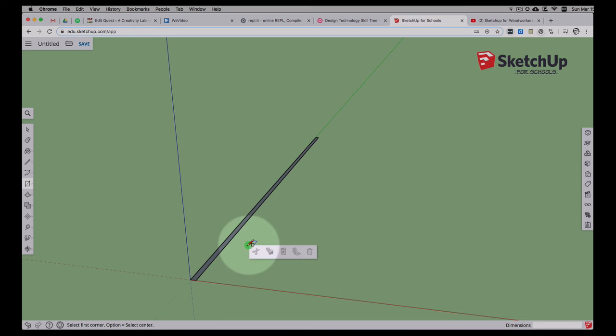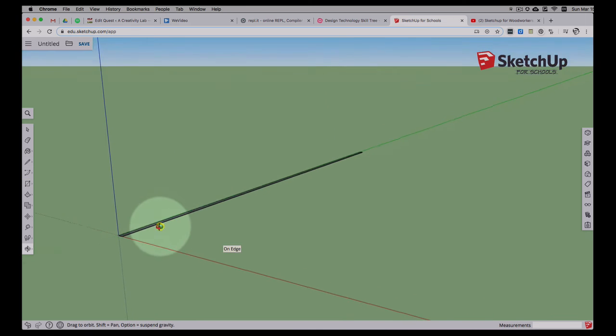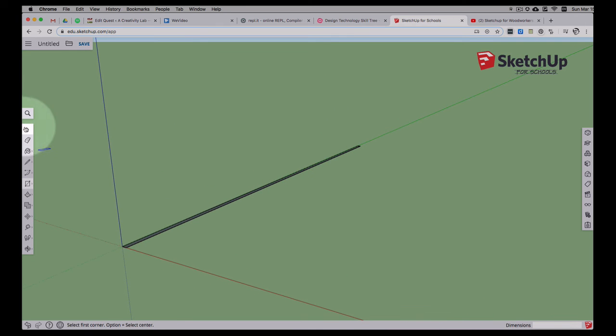Actually, that's probably not going to work very well for us. Let's make that 1 by 50 instead. So let's select that. I'll go from the lower right this time. Let's draw that again. Click, and then I'll type 1, 50. And that's a bit better.